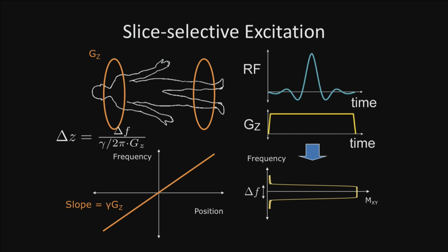Okay, so one way you can look at this is, we've got our RF pulse on its own. The RF pulse has some frequency selectivity. Here we're choosing a sinc pulse to get this basically rect type pulse profile in frequency. And with our gradient, now we've created this frequency versus position relationship.